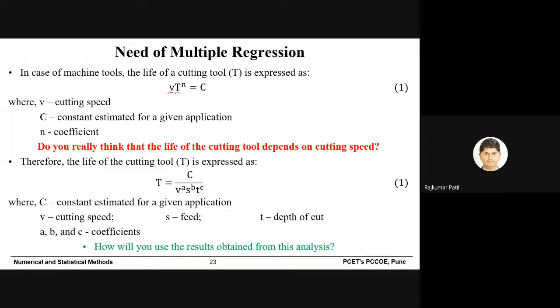Once you get that relationship, you can expand it for different parameters, and once you get that regression analysis, you can write a paper that for a given tool and given manufacturing operation, these are our important results, and through those results the user will be in a position to find out the optimum cutting speed, feed, and depth of cut to get the job with the desired accuracy or quality, and vice versa. So that kind of research work or paper you can write.